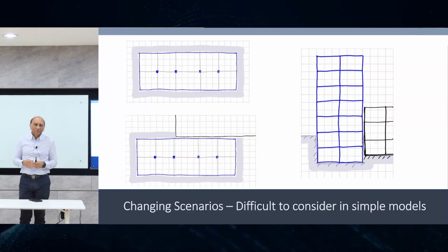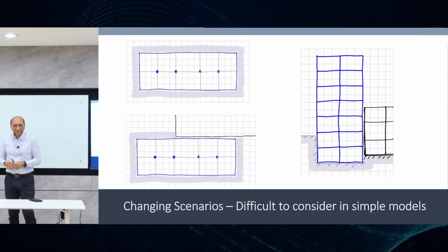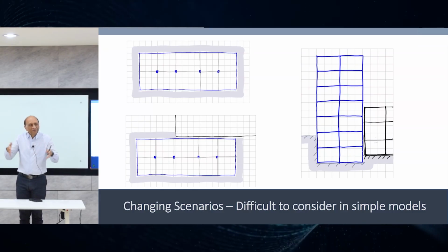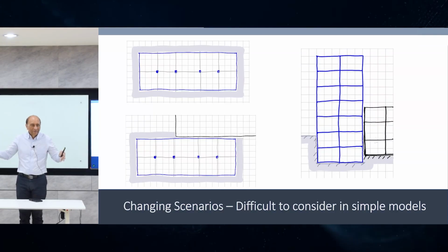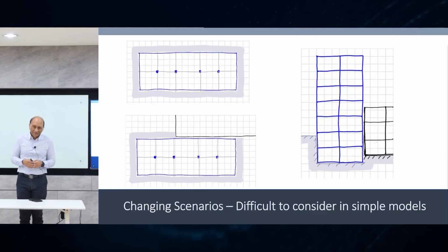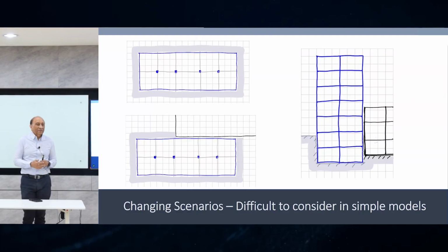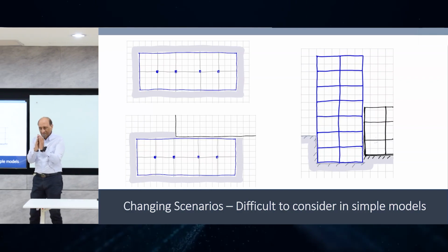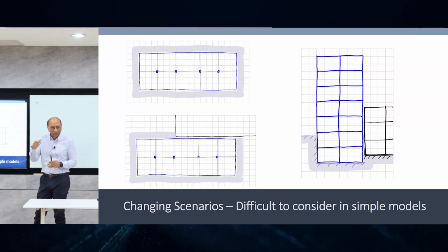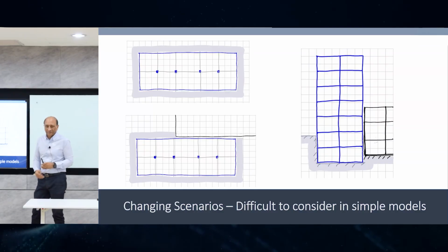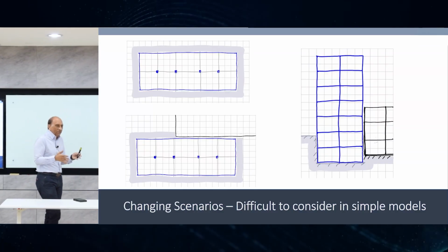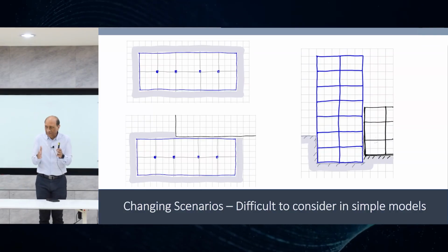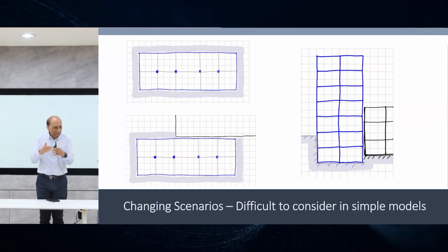Actually, we did a thesis on this issue: what happens if 5 or 6 buildings are connected together and behave as one with no gap, and what happens if there's a little bit of gap. It was interesting to study, doing the full nonlinear dynamic analysis to figure out what's happening if you have a block of buildings built side to side, not fully connected, but adjacent. We put the gap element there and did all that kind of stuff. That study was interesting to find out how the buildings can support each other if they are completely connected together without gap, at the same floor level.